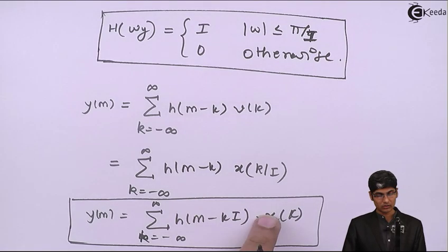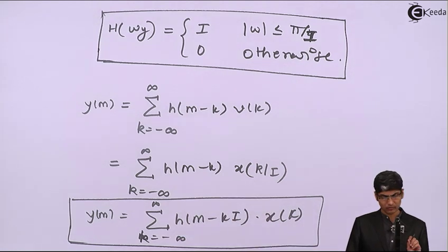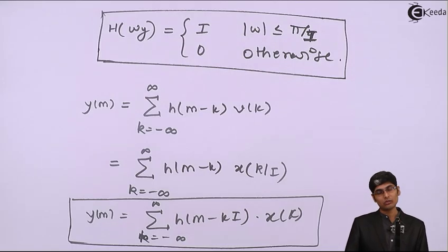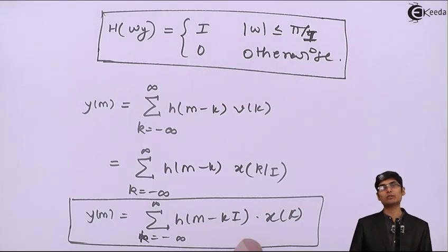So the transfer function of the filter looks like multiples of I. Okay. Now, even though the filtering is linear, that means the low pass filter that I have used in the interpolator or decimator is linear, the overall process of decimation and interpolation is time variant. So, even though we do the filtering as an invariant process, the total decimation and interpolation processes are time variant. Thank you.